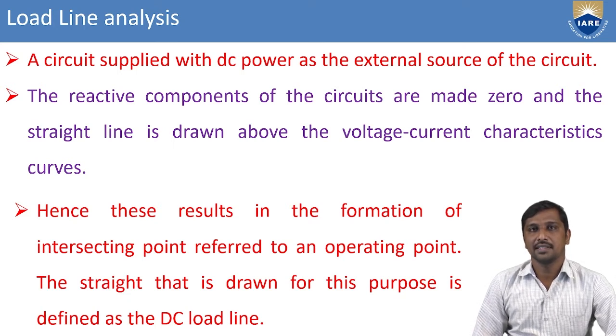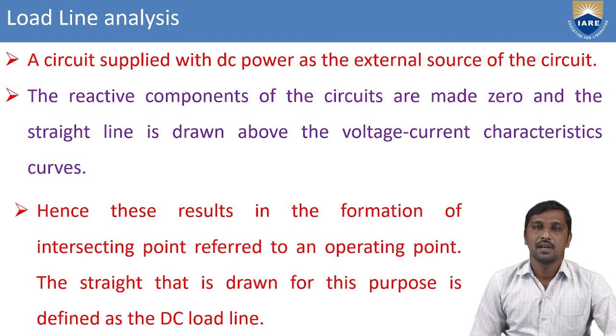From the characteristics, we observe that maximum current takes place across the forward biased PN junction diode, and no conduction takes place across the reverse biased PN junction diode. So we need to use the forward biased PN junction diode to observe the load line analysis, and by using it, we are going to examine the exact operating point for a PN junction diode.